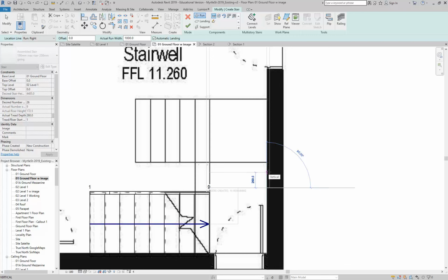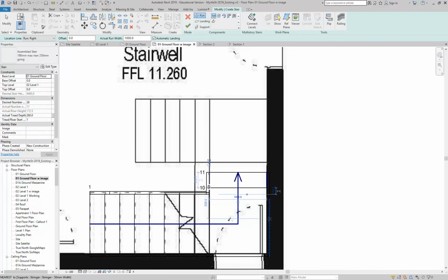That's all I can fit in there. And then now, coming around to this corner, I'm going to make sure I'm to the left of this edge here. So the basic concept there is that it creates the landings for you. But if you don't allow enough room for them, it won't connect them properly.